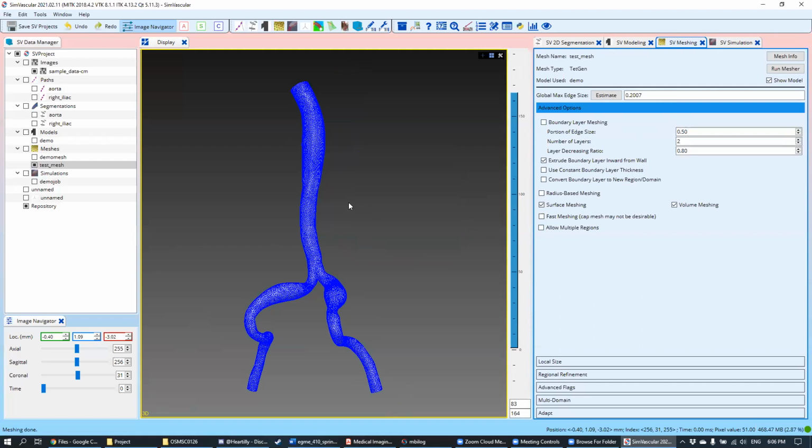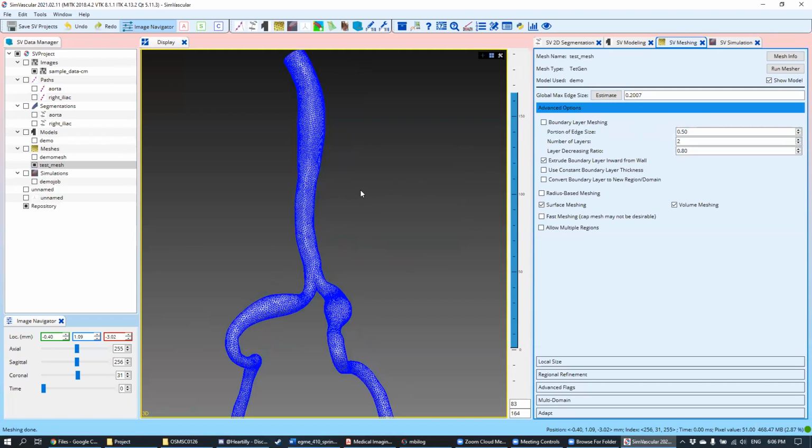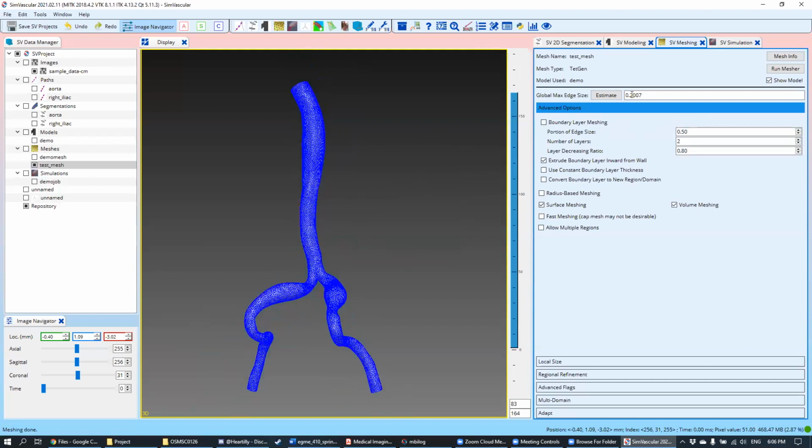All right. And so if you reduce the size of the elements, you're going to produce a mesh that's more fine or more coarse, right? Let me show you a case where we make the mesh more coarse. Instead of 0.2, let me manually change this to 0.3, and let me run the mesh again. You don't have to do this, this is just for your education.